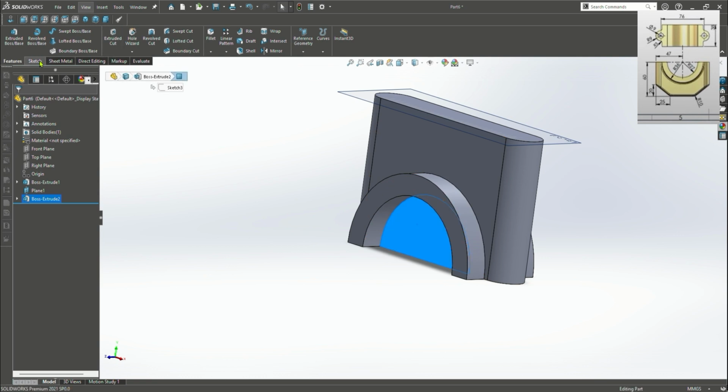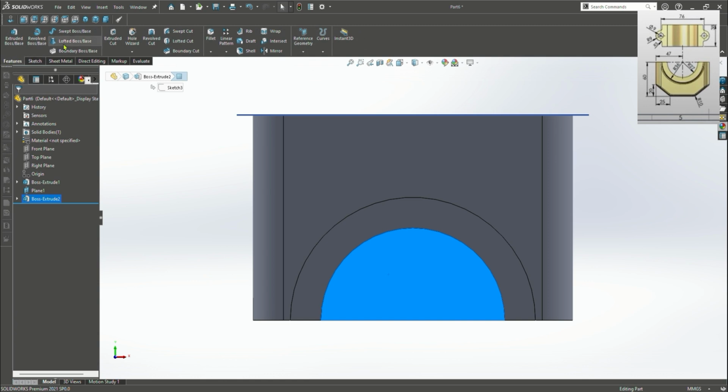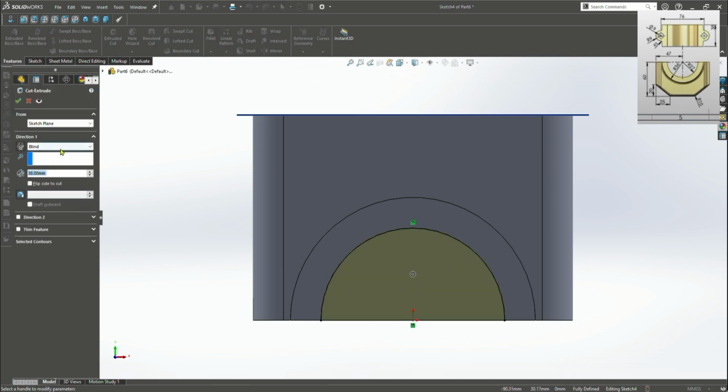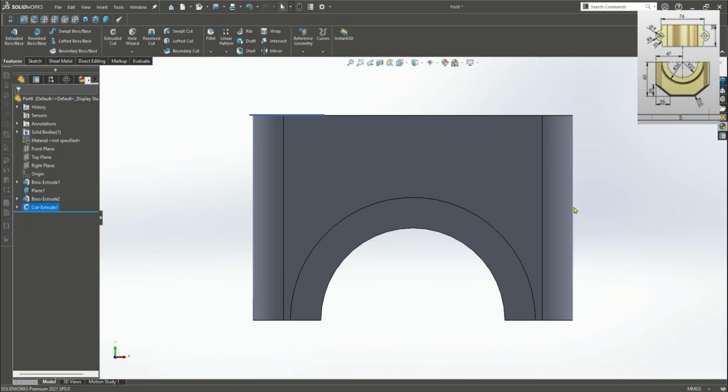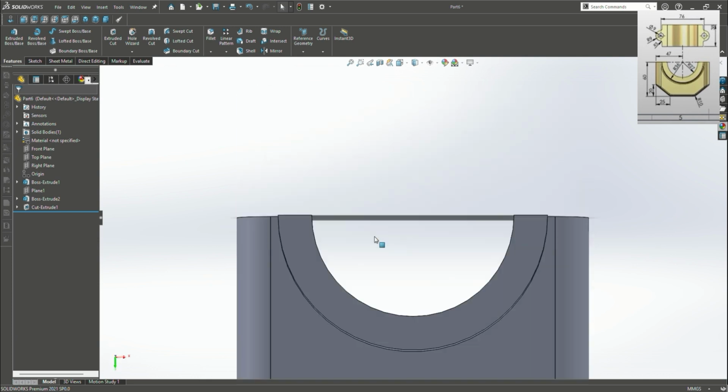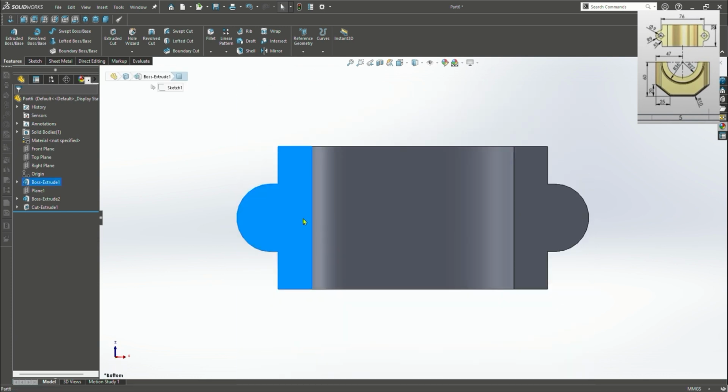But before that, we need to convert entities and eliminate this semicircle right here, because we need to put the crankshaft. Yeah, crankshaft. Before this, I said piston pin. It should be wrong. Okay, make a circle from the bottom plane. We're going to sketch.